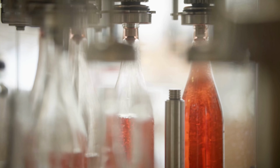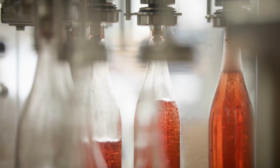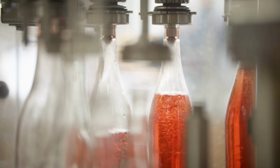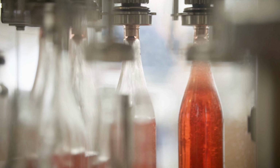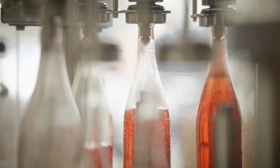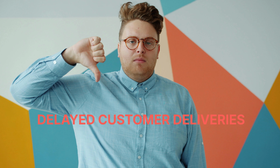Now, why is this important? Because Takt Time acts like a heartbeat of your process. It ensures that production is neither too fast nor too slow, but perfectly aligned with customer demand. If you produce faster than Takt Time, you create overproduction and excess inventory. If you produce slower, you delay customer deliveries.